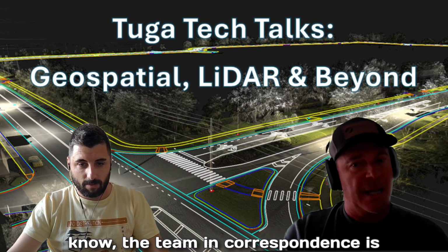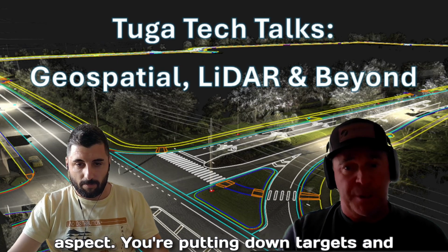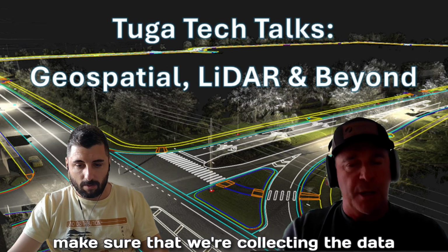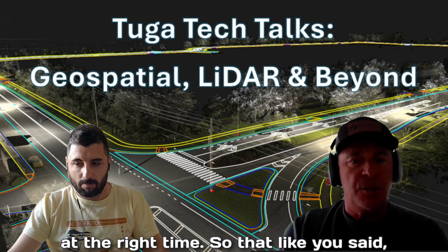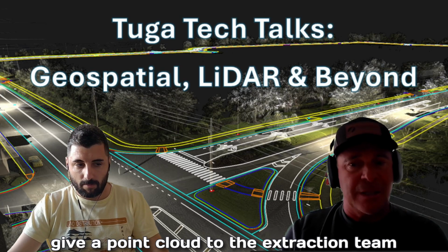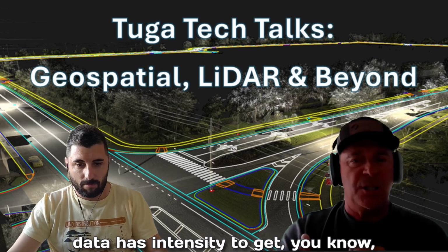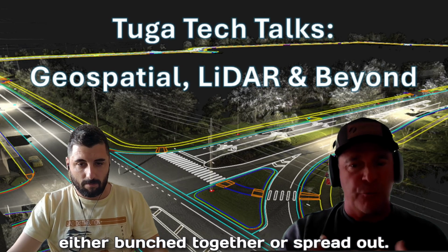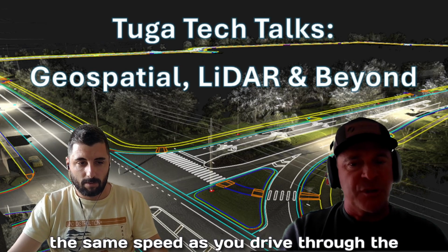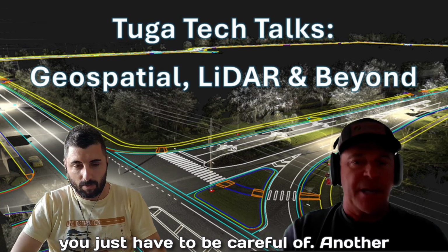The team's in correspondence, saying, hey, we see a lot of traffic. You might even see this during the control aspect. You're putting down targets and you're seeing a tremendous amount of volume, and then we have to adjust and make sure that we're collecting the data at the right time. Like you said, the last thing I want to do is give a point cloud to the extraction team that's full of cars. The data also has a tendency to get either bunched together or spread out. You really want to try to stay the same speed as you drive through the site and collect the data in a nice contiguous way. So that's another thing you just have to be careful of.